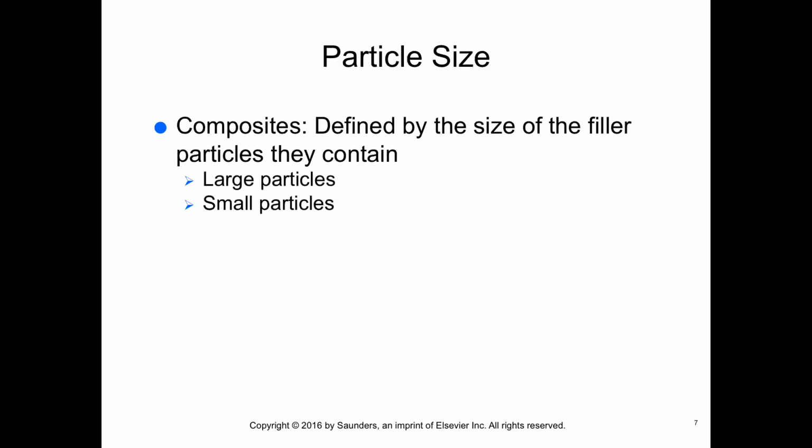The amount of filler in the resin and the amount of resin between the particles are related to how the material wears. Large filler particles tend to get plucked from the resin matrix at the surface when the restoration is under function. Larger particles cause the finished restoration to appear dull or rough. Smaller particles are not as easily pulled from the resin and therefore cause fewer voids that contribute to wear. Smaller particles are packed more closely together, thereby exposing less of the resin matrix to wear. The smaller the particles, the smoother the surface is.